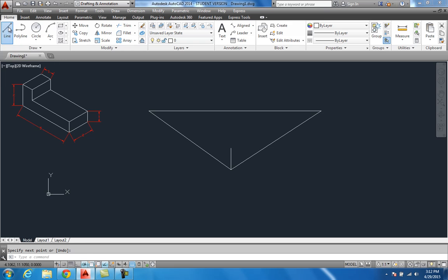So basically, now I want to grab this point, and again, I want to send it home. Just like that, because it's the highest point. Okay? Well, if you'll remember, this thing right here only comes up 1. So we're going to come up 1 inch. I'll just type in 1, enter. So there's that. And here's this one going back as well. Now, to remember, alright, that one's going back here.